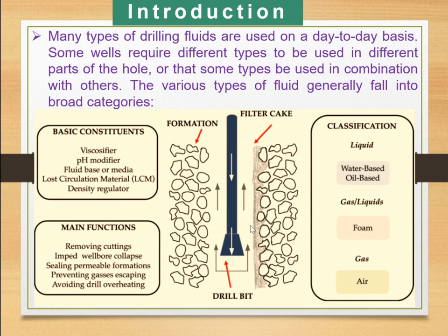At that time I don't need very high viscosity, otherwise the formation will be damaged. When formation pressure is high, to resist water flowing into the borehole, we need high dense material. So depending upon the formation pressure,